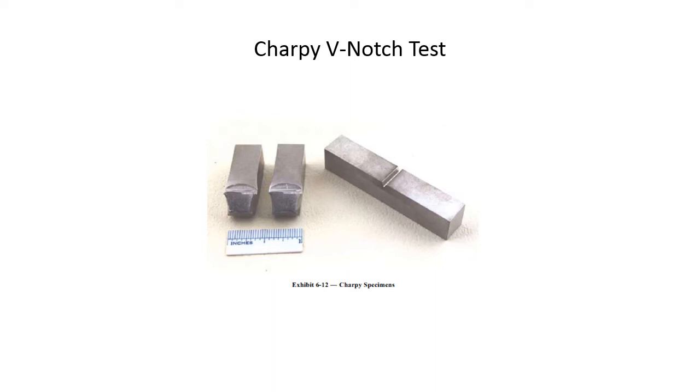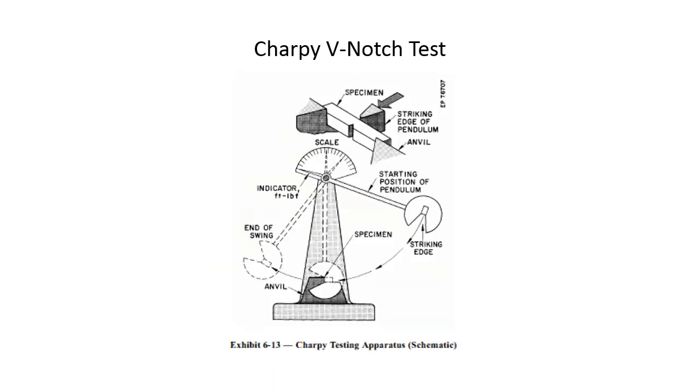And like I've said before, you don't just do one impact test, you do multiple impact tests because the scatter of the data that you receive can be a little weird. And I mean weird, you might have one test sample that's just nowhere close to what the others are. So that's why you do multiple tests.